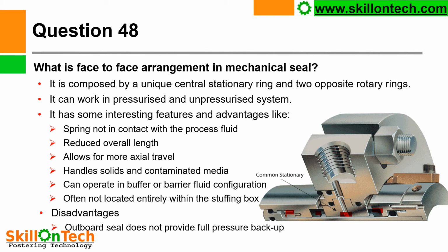It has some interesting features like a spring not in contact with the process fluid. You can see here the springs will not be in contact with the process fluid. Reduced overall length. The length of the mechanical seal is reduced. Simple design allows for more axial travel, handles solid and contaminated media, can operate in buffer or barrier fluid configuration, often not located entirely within the stuffing box. There is one disadvantage: outboard seal does not provide full pressure backup. So these seals can be provided with buffer fluid and barrier fluid configurations.